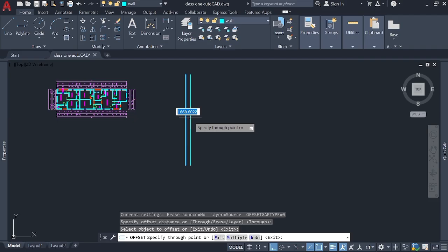So as an engineer, you need to know what your client wants, and you need to be economical while designing, because you cannot be wasting money using 225 millimeters while you can use 150 millimeters and the design will still stand. You get? So it is economical because the load will not be much. It's just the roof. So 150 millimeters is okay for the walls, but for the upstairs 225 millimeters is okay.